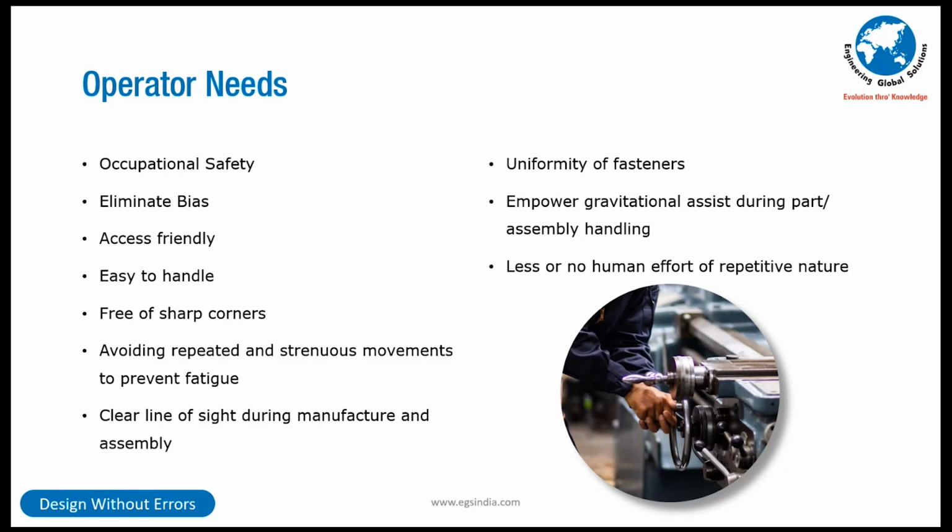So we can't allow that to happen, right? We need to look at it from that point of view as well. So if I'm designing a machine, I need to put up a step-up platform, which is already available, so that the person does not go in and remove the component by exerting more lower back effort. He's bending forward and then removing the component.